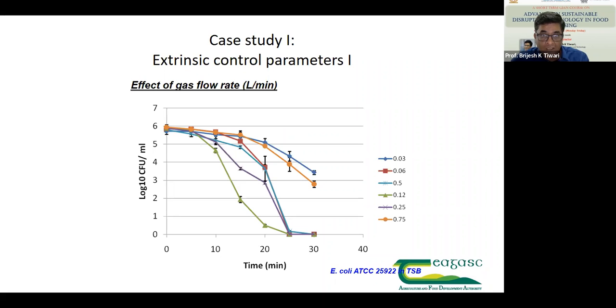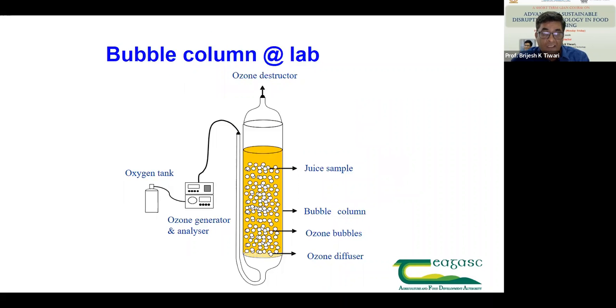That means, I just go back to this reactor once again, another application is when we introduced ultrasonics within this particular chamber. That is one of the processes of AOP, that is advanced oxidation process. What we found was it was very, very efficient in oxidizing the liquid, and we used that particular system for treatment of water, especially for reducing the BOD and COD of the wastewater coming out of the food industry. So agitation is also important, which is also controlled by the type of bubble it forms.